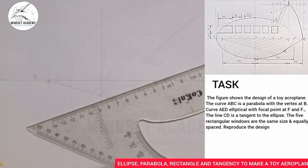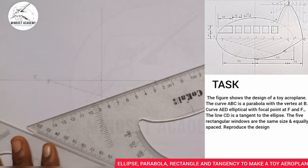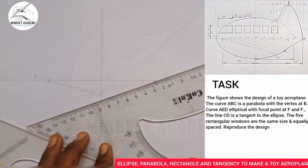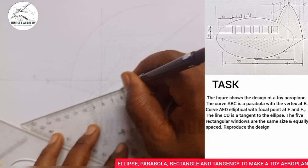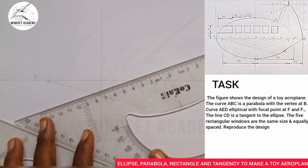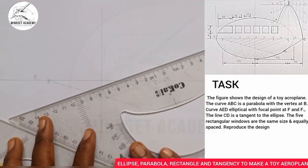I'm going to take another set square and I'll place it at the base here. Hope you can see that below here, right? Then I'll start moving it upward to ensure that I draw lines parallel to the initial line I drew. So I'll start moving it from point to point.